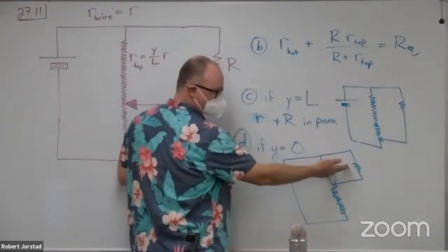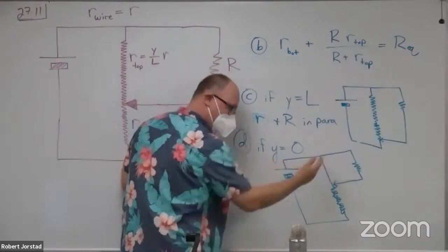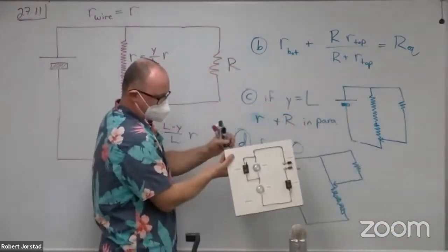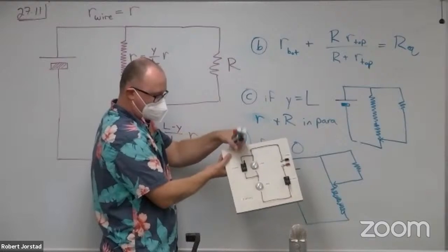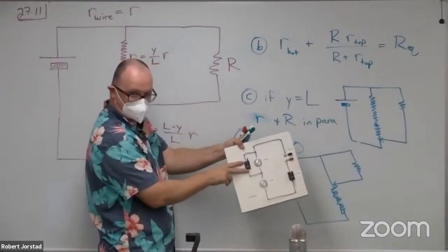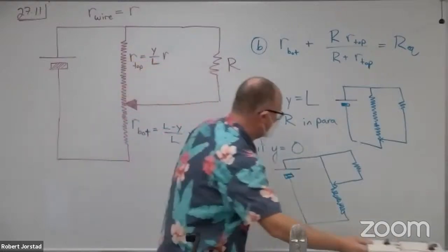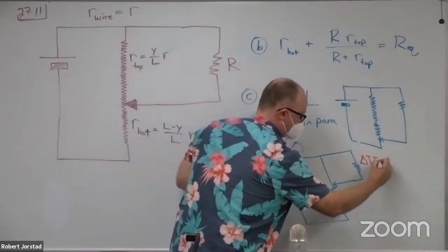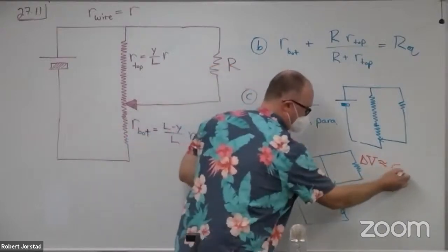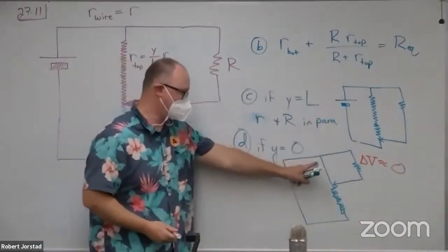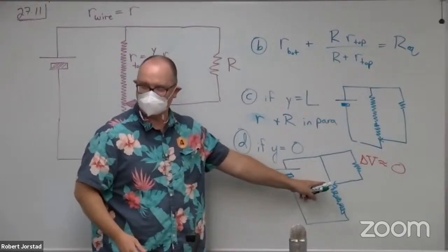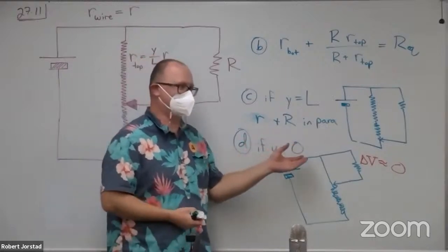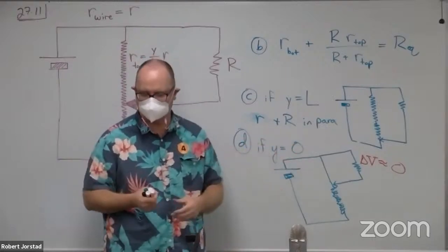What voltage is across this one? How bright was this bulb when I shorted it? It's off. It's the voltage across the switch, which was 10 millivolts, remember? In this case, the voltage is approximately 0. It's in parallel with nothing, right? There's no voltage drop here. In reality, there's a tiny fraction of an ohm associated with the wire itself.